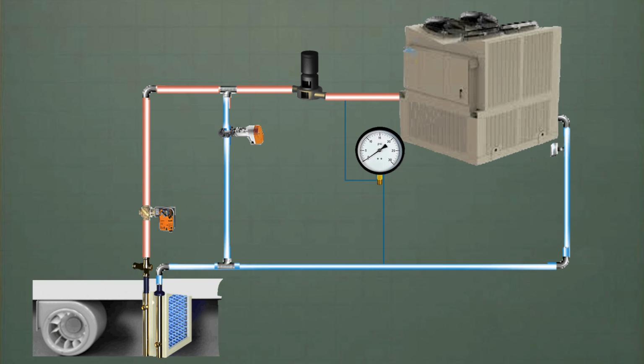So since you're there, the loop is hot, all your sensors and transducers are calibrated, you might as well check the refrigerant charge while you're there. That way you don't go back, put in your bypass valve, leave the job, and then in July you find out the thing's low on charge also, that you overlooked. It takes you an extra 10 minutes now because the loop is hot, everything's already calibrated, and you can just go ahead and check your charge while you're there.